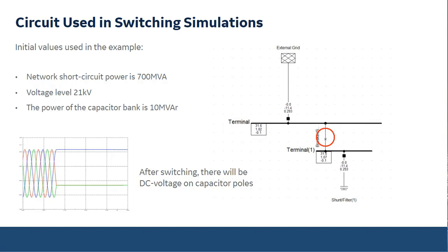When you switch it off, the voltage will not go to zero. There will be high voltage, and in some phase it will be almost a peak voltage, at least close to peak voltage when you disengage the capacitor. This is the reason why you have the issues here. Now we have to think about this switching transient.